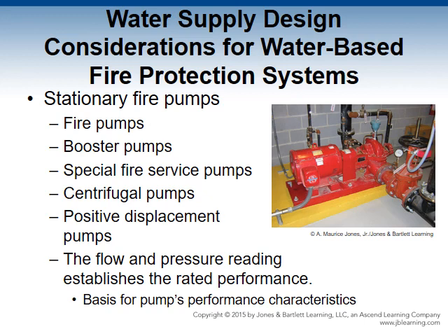Positive displacement pumps are well suited for high pressure applications, but unlike the centrifugal pumps, they can build unwanted pressure on the discharge side of the pump. They should be equipped with an internal or external pressure release mechanism on the discharge side of the pump.